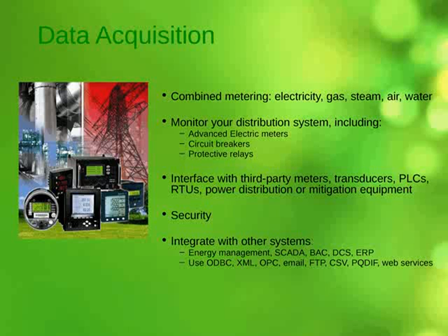And then there's the integration side of it, in that not all meters are created equally or the same. So you look at standards for communication of this data, such as ODBC compliant databases, XML format, OPC, email, FTP, CSV, PQDIF, and web services. A lot of alphabet soup there. But these are all different types and formats of data that are out there that you want to be compatible with under the data acquisition term. Next slide, please.